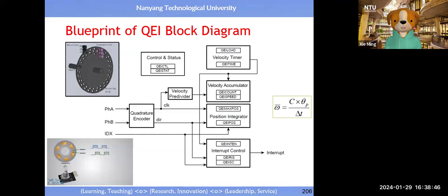So it means whatever you read from this microcontroller is actually C divided by delta P. Once you get C divided by delta P, based on the sensor you use, you must read the data from your digital sensor to find what the delta P is. Then you must multiply delta P times this, and you get the actual angular velocity. Pay attention to this, because the microcontroller manufacturer may not know the sensor manufacturer.